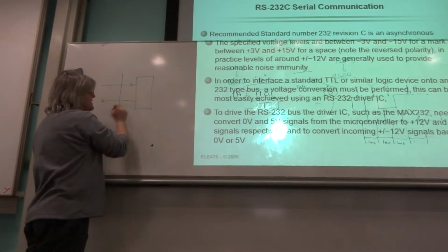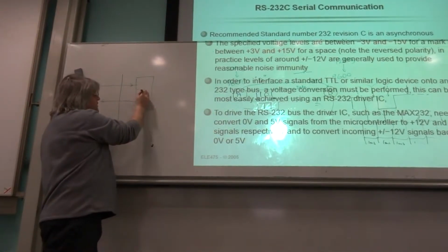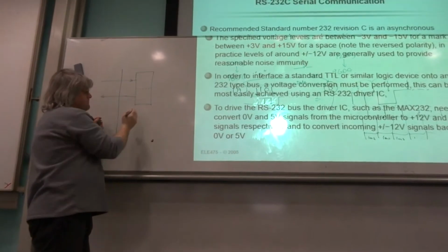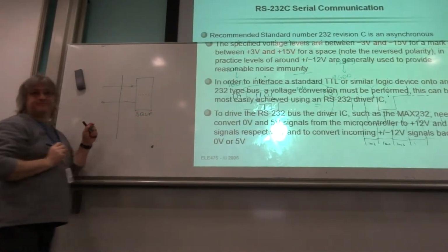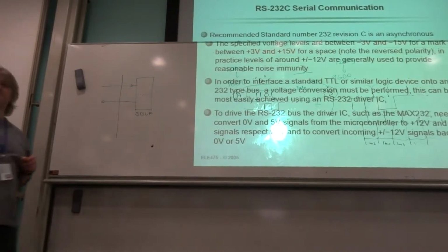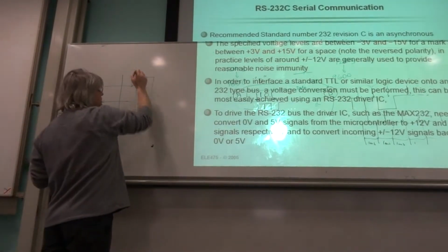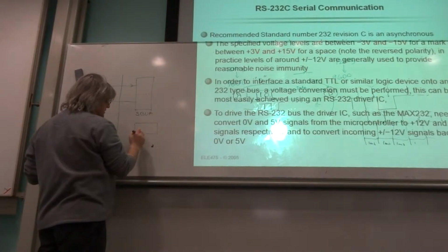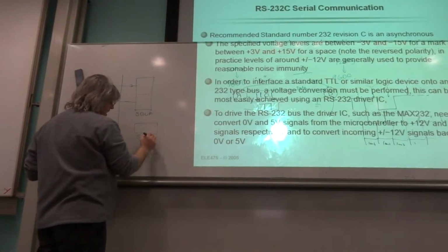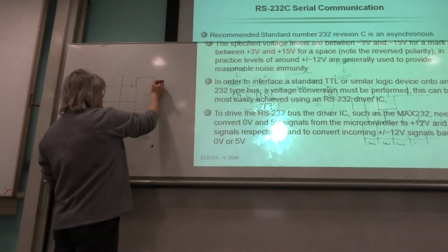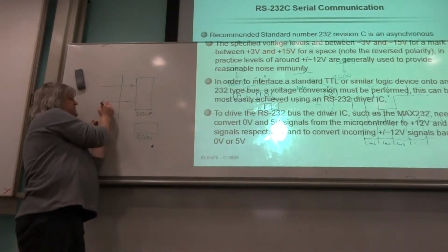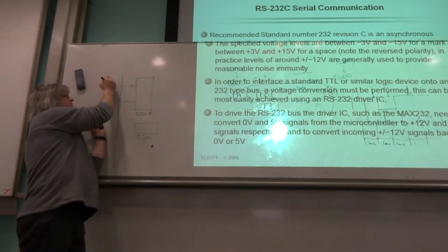And they're both connected to a pair of registers which collectively share the same name, SBUF. Okay? And associated with this, there's also a special function register called SCON. So this would be the TXD, and this is the RXD.